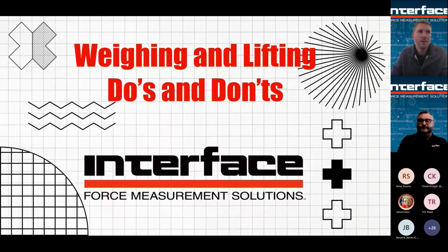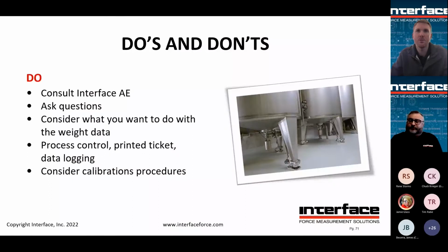Next slide. So, some of the do's and don'ts when weighing or lifting. Do consult Interface. Especially if you're not so familiar, we will be happy to help you choose the right equipment, the load cells, the weigh modules, instrumentation, and tell you the questions to ask your customer. Again, some of the questions that need to be asked: the live load, the dead load, the number of supports, washdown, material being used, temperature, hazardous environment, type of vessel, tension or compression, what is attached to this, mixers, shakers, rigid conduit piping, will there be shock loading? And then always find out, what kind of increment do they need to weigh by?